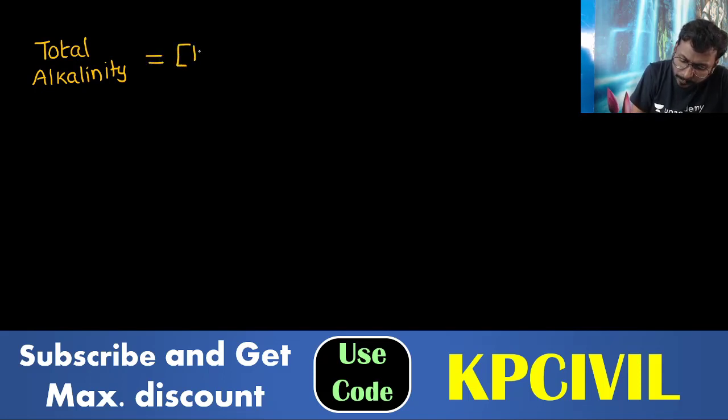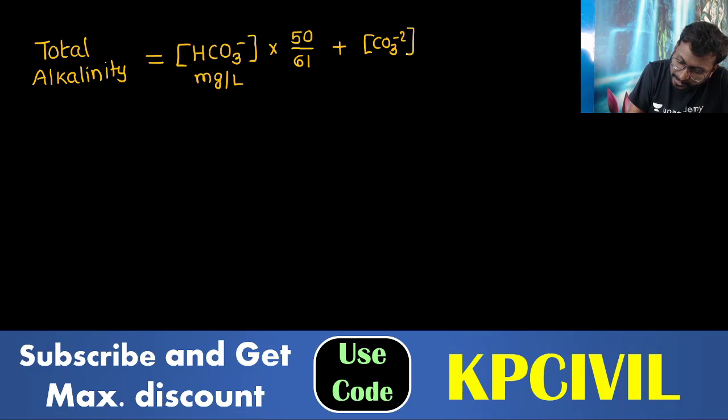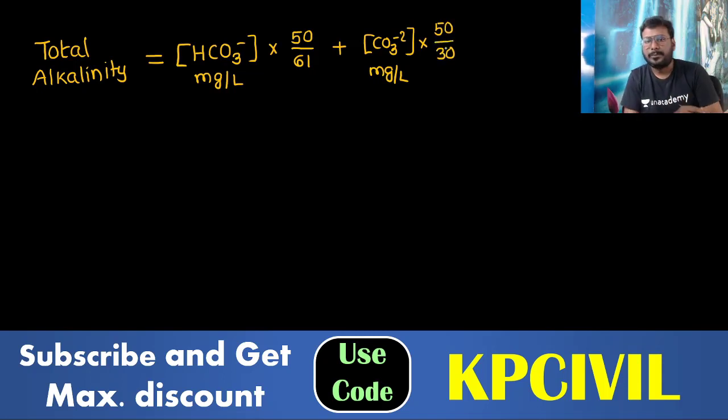What is the formula? HCO3 minus, taken in milligram per liter, into 50 by 61, plus CO3 minus 2, taken in mg per liter, into 50 by 30.